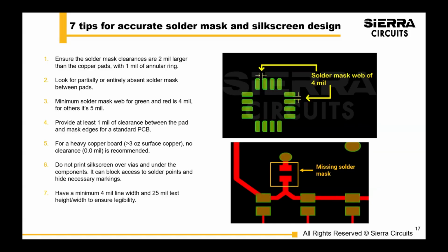But basically, I'll give you a quick off the slide example. There's something called peelable solder mask, which is a real pain for any fabricator to do. But if the assembly must or needs a very clean area post assembly process, either you have to buy a fixture or you can use this process of peelable solder mask and keep that area very clean up until the end of your manufacturing process. So these are the type of decisions and trade-offs you can make if you're a fabricator and an assembler.